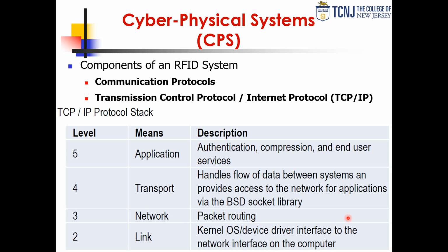It abstracts all the software from the specific connectivity to the communication medium, whether it's wireless, wired, optical, it doesn't matter. Because there is a standard, what you call an MII, a media independent interface, independent of the connectivity and transmission and reception medium, that has been defined, and that is the bottom of the link layer.